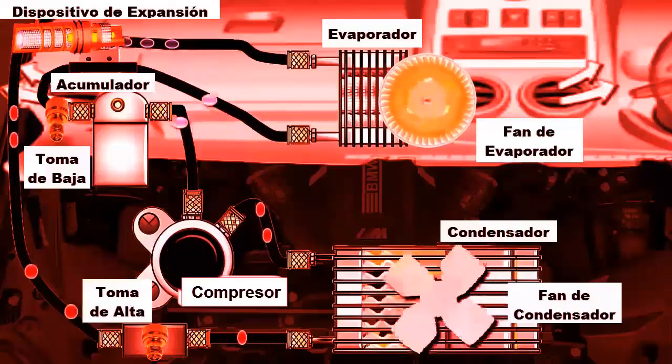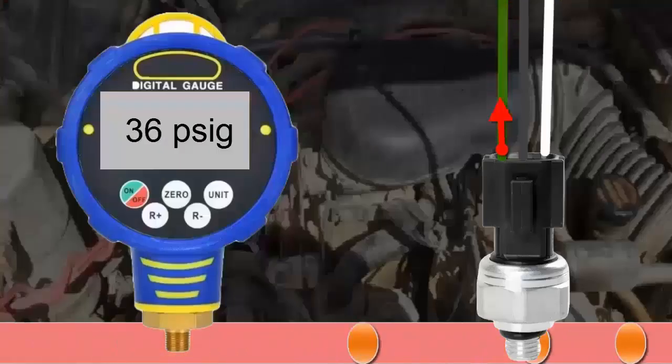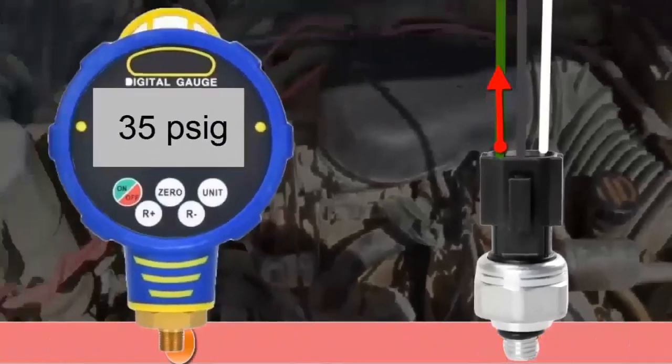However, code P0534 can also activate if there are electrical problems, such as faults in the refrigerant pressure sensor, faulty electrical connections, or a deficiency in the sensor's power supply.